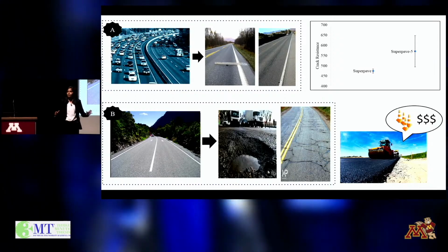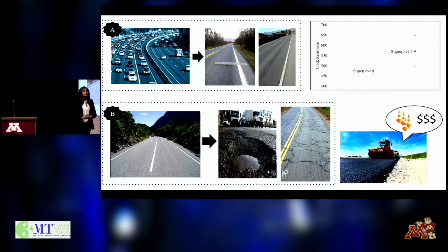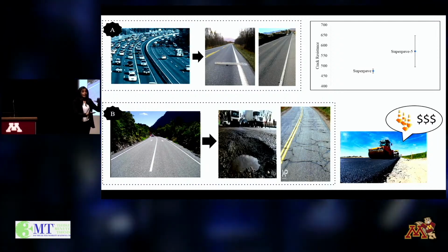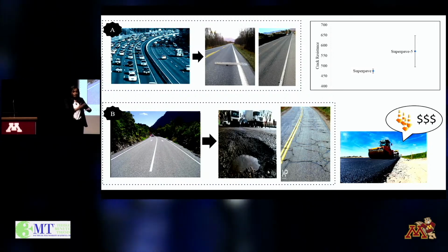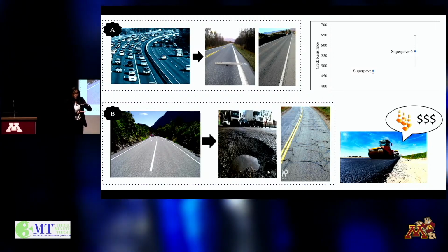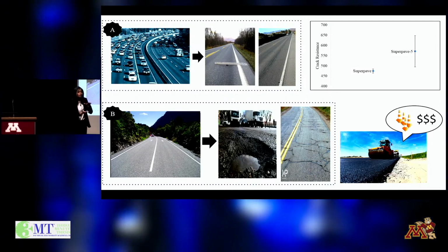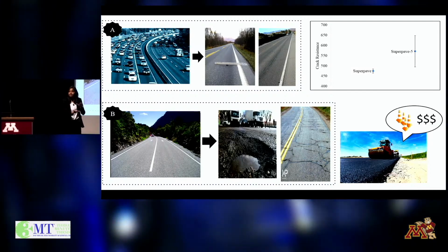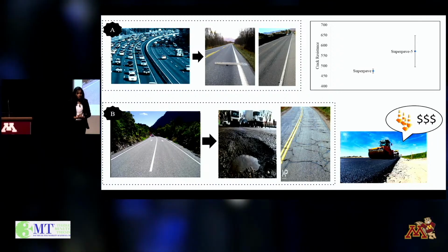What actually happens with the high volume road design is that we make asphalt mixtures with 7 to 8% air content and place them on the field. Over time, due to heavy vehicular movement, the asphalt layer undergoes compression. The 7 to 8% air content reduces to 3 to 4% air content. And this dense asphalt layer protects the pavement from failure due to weather changes.